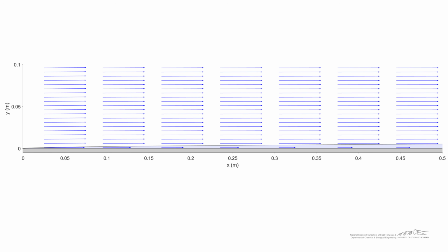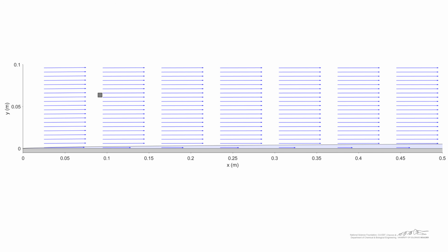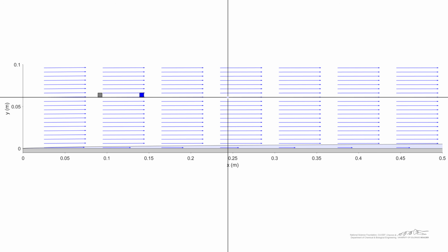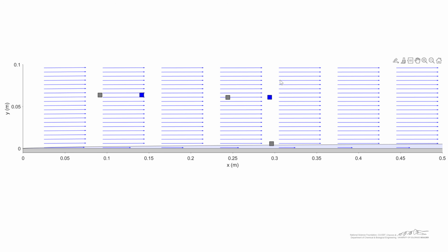Let's look at a case in which we've got a really large Reynolds number. In this fluid, it turns out I used properties for liquid mercury. This fluid's got a really large density and a really small dynamic viscosity. If we look at it, we could examine a location within our velocity profile. And when we look at the movement of that fluid, it just translates, and there's no deformation of the fluid itself. So no matter where we pick, we find that the original shape doesn't deform at all. The only place in which it deforms is near the surface, or within the boundary layer there.